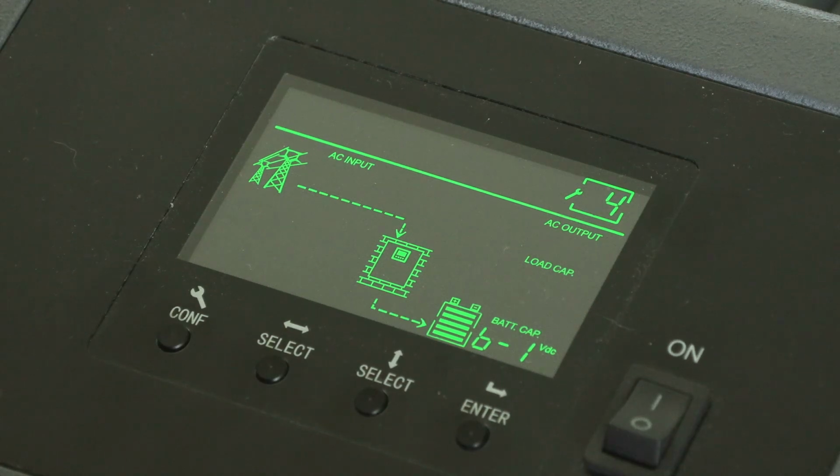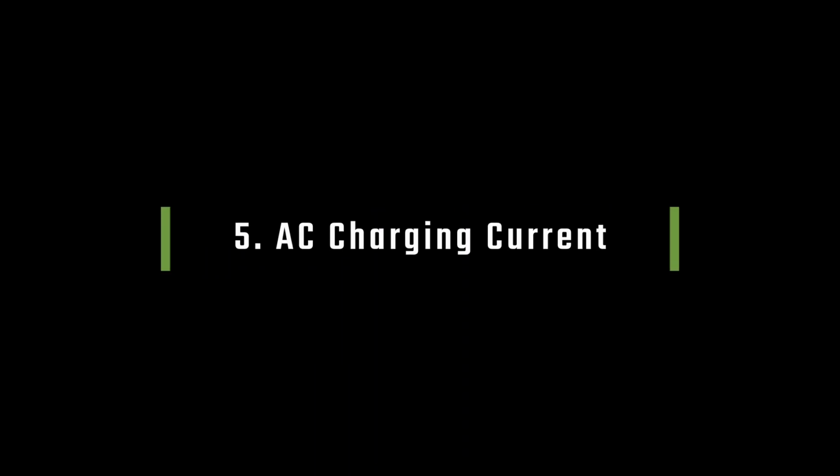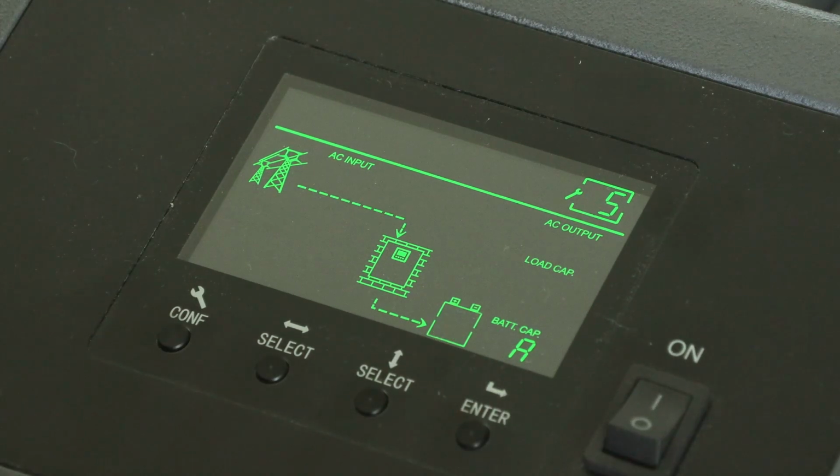Menu 4 is going to change the AC charging voltage for your batteries. For the bank, do not change this unless instructed to do so. For an inverter, refer to your owner's manual and match settings to your battery specifications. Menu 5 is going to change your AC charger current. This adjusts the charging current for your battery bank.